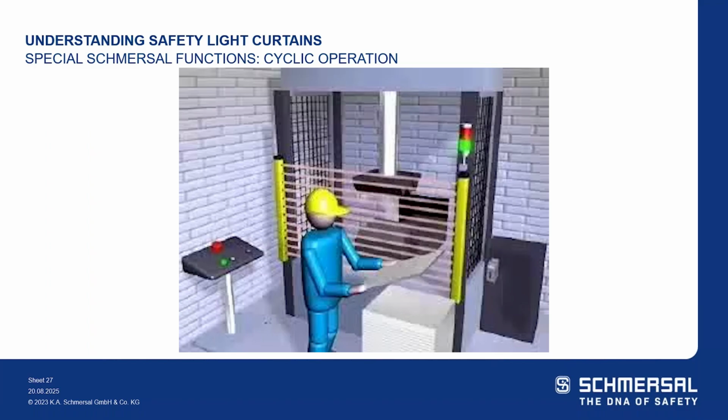The example that I'll play again shows a cyclic operation of one interruption. So the light beams will be interrupted once before a machine cycle is initiated. You'll notice that the fault occurs when he pops in a second time during an active cycle. So I'll play that again.